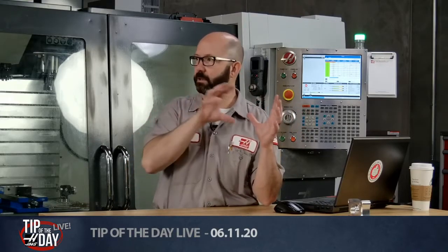That was helpful years ago, especially when people didn't have perfect post-processors set up, where you had to pay $1,500 to have all the codes that were working fine for your main spindle rewritten for the sub spindle. You had to have these special post processors to get your lathes to run if you had a sub spindle. On the HAAS machine, it's just super easy. Your post processor changes one thing. Add a G14 and it all runs on the sub spindle.